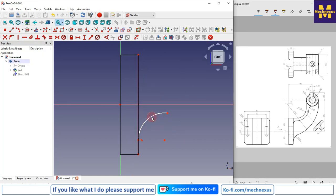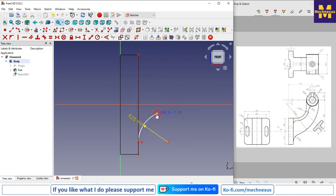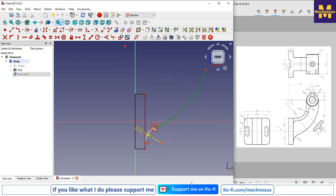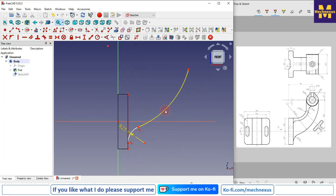This is the 25, so I will select this and give the radius 25. Then I will again draw a radius of R100. I will select the 3-point arc and make it tangent, and then I will again draw a 3-point arc.